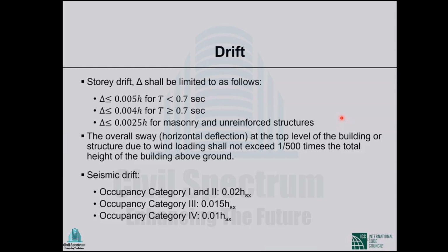If I pull a structure in one direction and remove the force and make it free, it vibrates freely without any force, goes to the other direction because of vibration and comes back, and the time required to make one cycle is called the period of the structure.